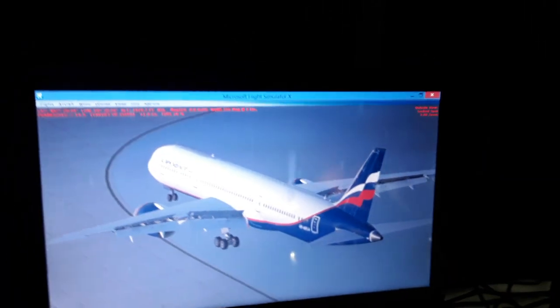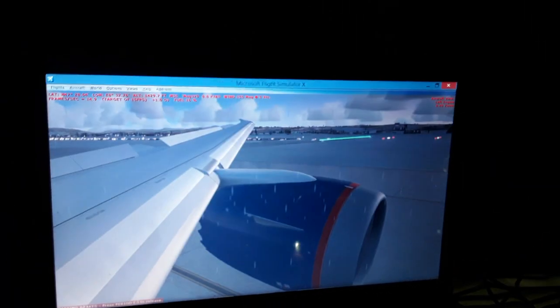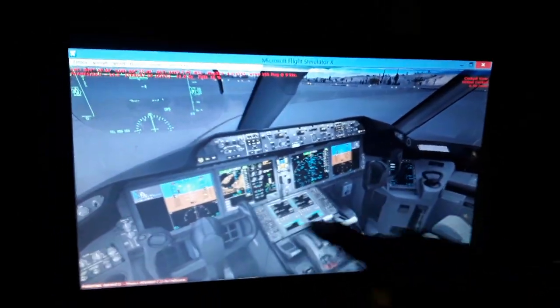So I will show you all these things. Maybe I have to start with the flight management computer. So I insert all the data of the aircraft for this flight. That includes the takeoff gross weight, which includes the empty weight plus the passengers plus the cargo plus the fuel on board. The fuel on board includes the trip fuel, the reserve fuel, and the taxi fuel.